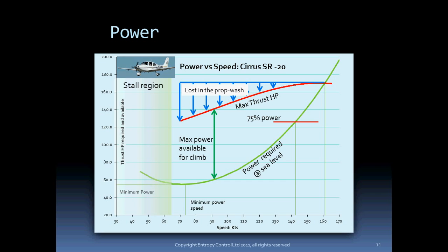The power performance of aircraft has a subtle effect in slow flight. Say you're flying VFR and the weather has closed in, driving you to a low altitude. Perhaps visibility is poor and maybe you're a bit distracted looking for an airfield, so you're flying slowly. You're trying to maintain altitude, but you notice that you have sunk a little. Instinctively you raise the nose.